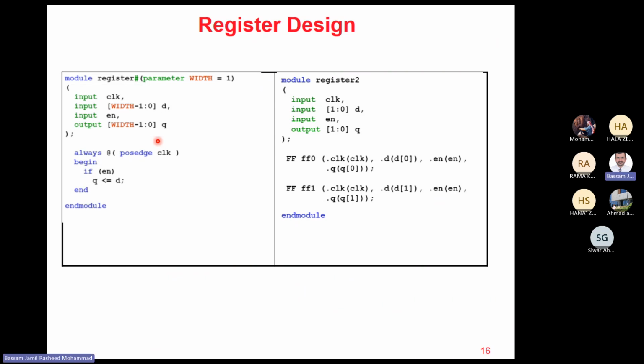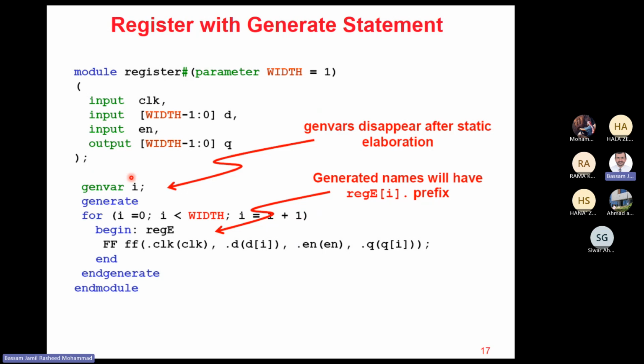So what else do we have here? Registers. If we have multiple flip-flops, then the name changes from a flip-flop to a register. That's the convention. It's the same design here, but just multiple bits. Now, one thing Verilog offers you, if you implement in hardware a lot of instances, is this generate here. I have used it in the past. It's kind of nice, but you really have to be accurate. I would consider these constructs to be useful for those with some experience with Verilog.